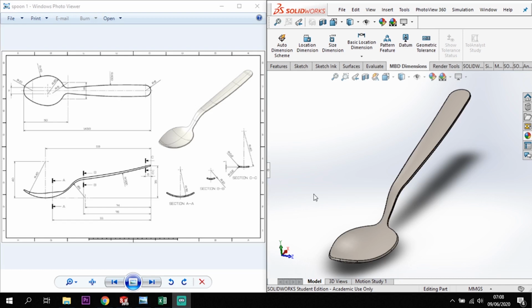So the way that I like to think about surface models is that with my sketch tools I am going to lay out some sort of skeleton or frame that I am then going to lay the surface over, or in terms of the body, I'm going to lay the skin over the top.